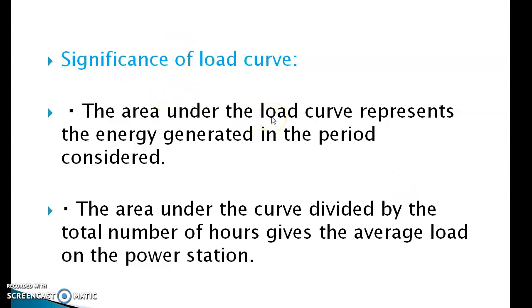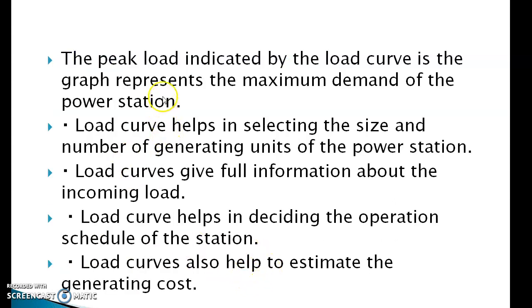Significance of load curve. The area under the load curve represents the energy generated in the period considered. The area under the curve divided by the total number of hours gives the average load on the power station. The peak load indicated by the load curve represents the maximum demand of the power station.